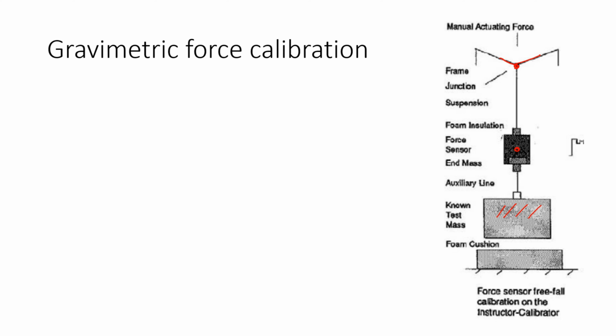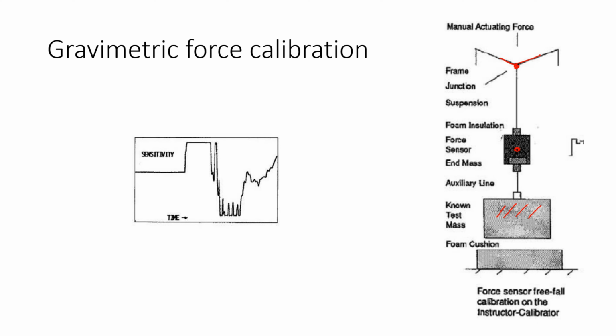We're going to take our hammer and hit it down here, and we typically get a response that looks like this. So we're going from the equilibrium position into free fall, and this is the moment when the gravitational pull is experienced by all these masses here. Now, because this is a load cell, it's in fact not measuring the acceleration. It's measuring forces.